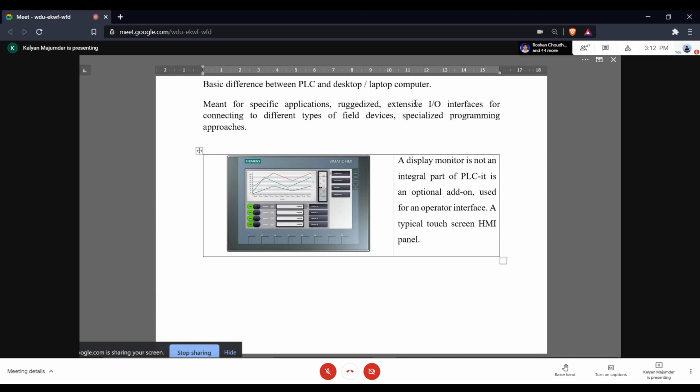Second is, it should be capable of operating at high levels of humidity, as long as it is not condensing. Condensing means the humidity condenses on the electronics. As long as it's not condensing, a humidity level of 95% is okay for a PLC. It should be capable of operating in an extremely noisy environment, electric noise. You go to an industrial environment, you have a large number of motors running at very high rates. You could have